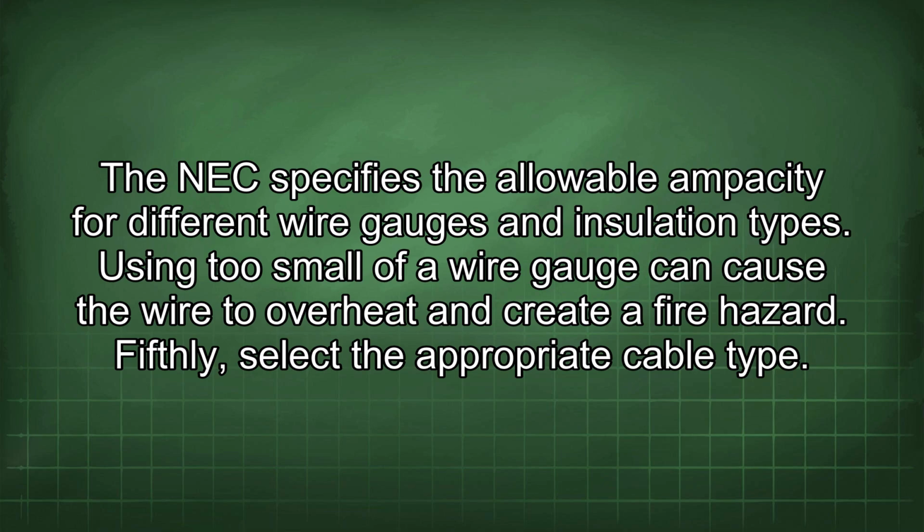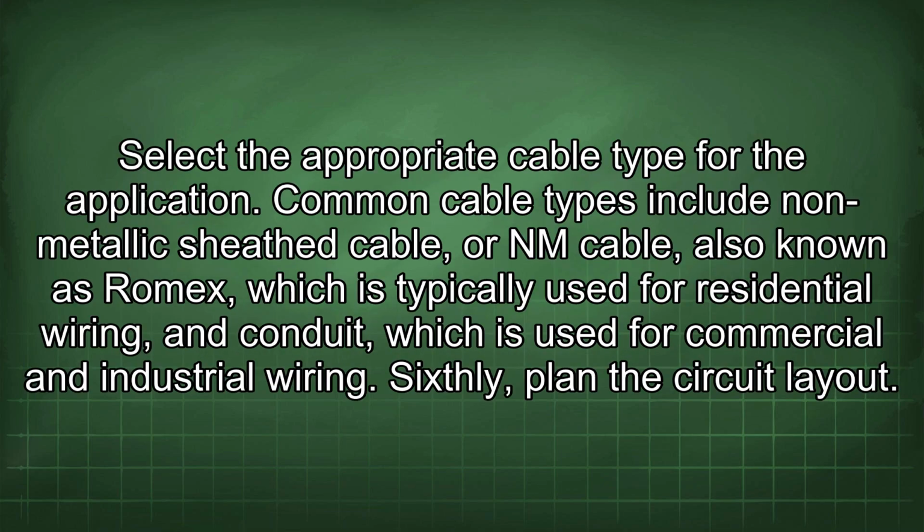Fifthly, select the appropriate cable type. Select the appropriate cable type for the application. Common cable types include non-metallic sheathed cable, or NM cable, also known as Romex, which is typically used for residential wiring, and conduit, which is used for commercial and industrial wiring.